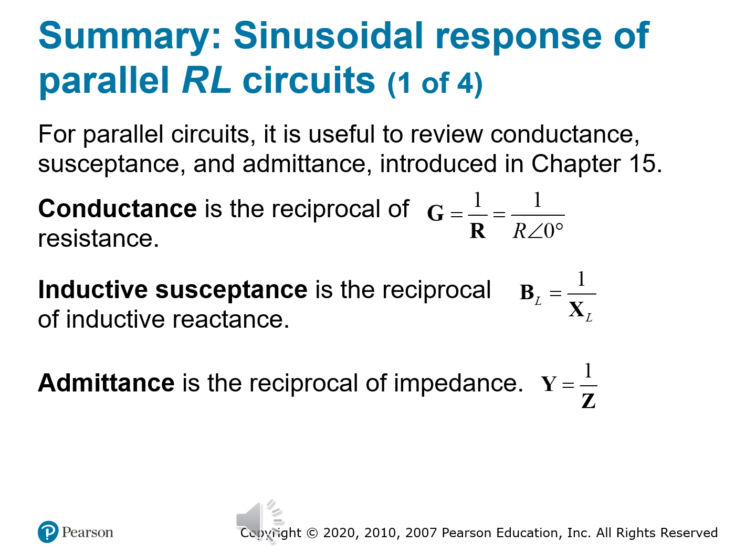And then the last one is admittance, denoted by Y, and this is a full counterpart to impedance. Forgive my accent, people. It's a complex quantity. It combines G and B, just like Z combines R and X. So we get this new complex form: Y is equal to G plus jB, right? We use these because in parallel circuits, current divides and total admittance adds just like resistors in parallel. You add admittances, you don't add impedances here. This makes phasor analysis in parallel circuits simpler, cleaner, and better suited for frequency domain work.